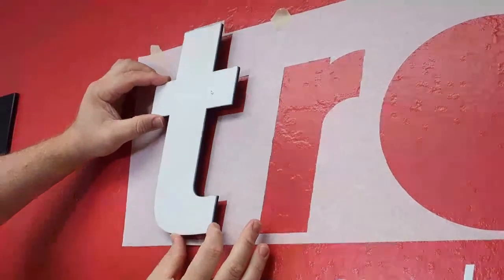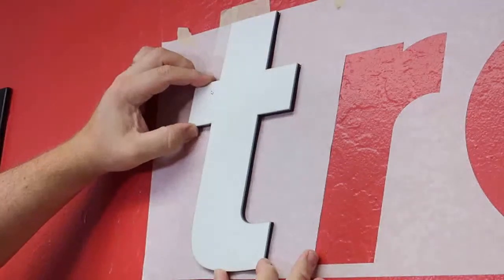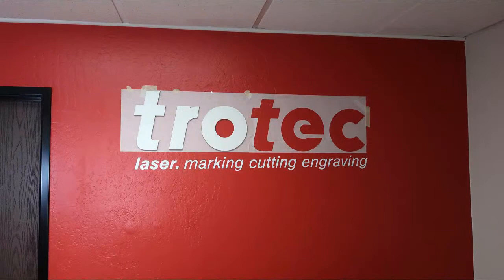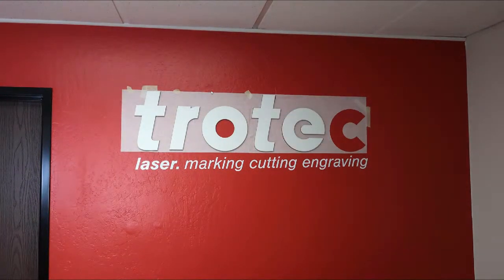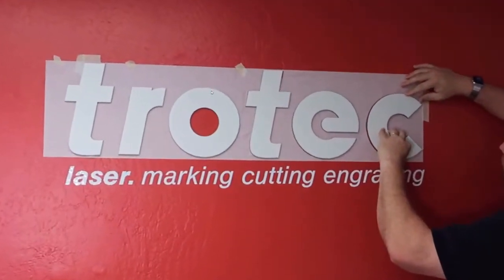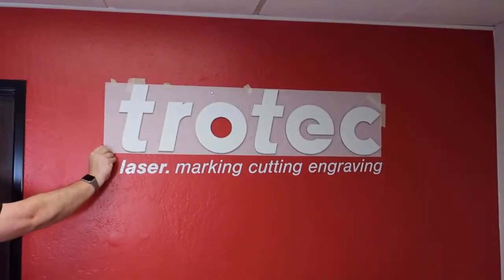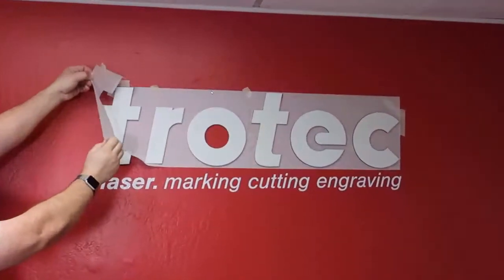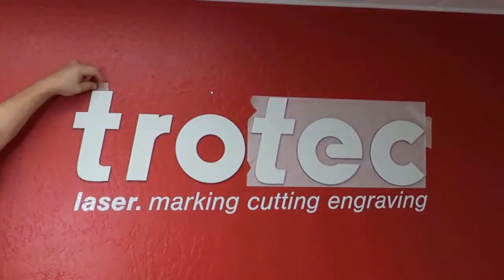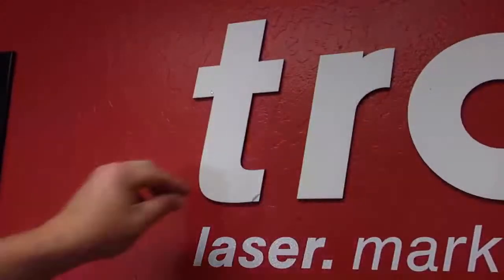Then we're going to peel the VHB adhesive on the back side of each one of the letters. And then we're going to apply them to the wall. So there we go. We've taken each one of the letters and applied them to the wall, removing the double-sided adhesive on the back side of each one. And this is going to give me my position and orientation. And you don't have to use application tape. Like I said, you can use anything. Once you've got it adhered, now you can just remove your template off of the wall. And we now have our raised letter dimensional sign adhered onto the wall.